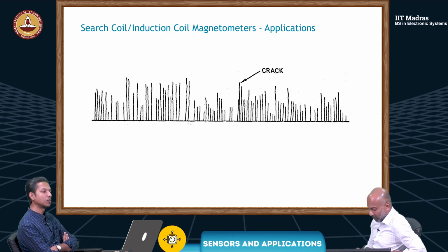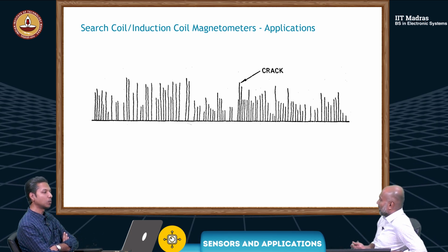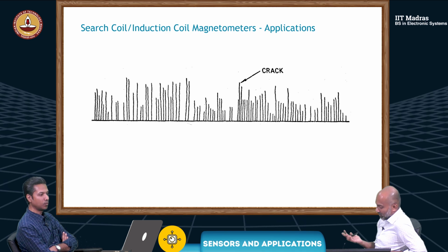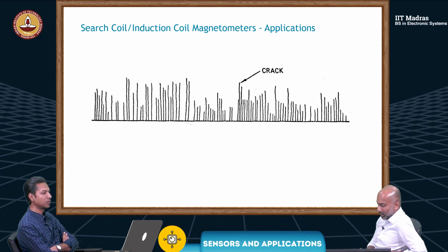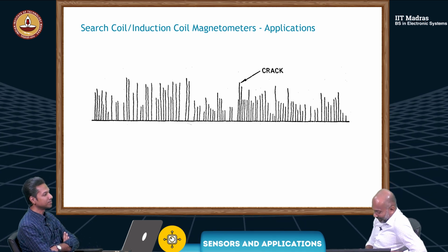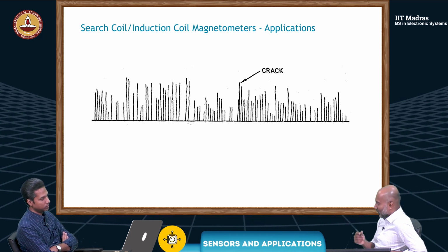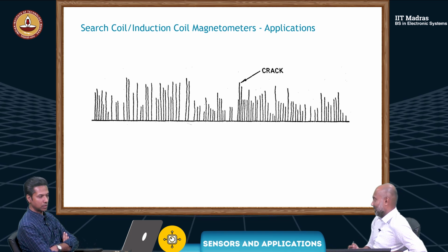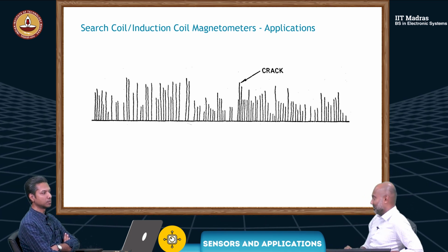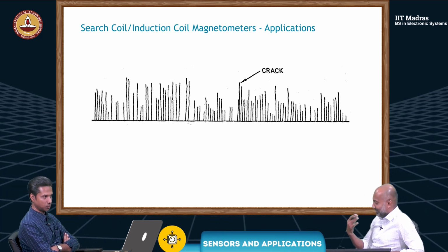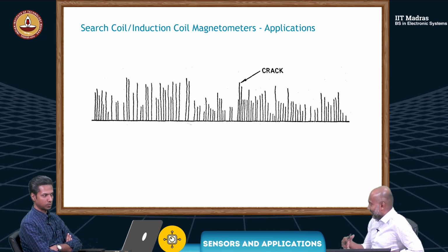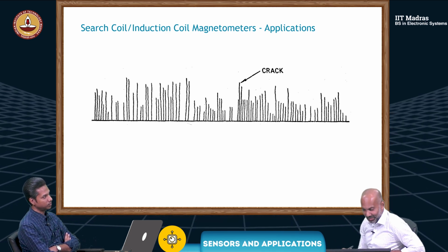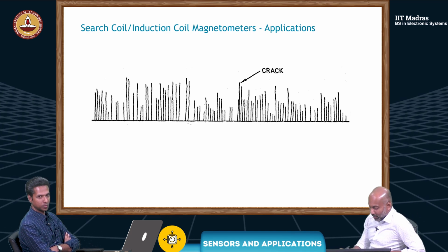Now, we have already talked about 3 different variables, right? Conductivity, permeability, and liftoff. Now we're talking about cracks. Now, we talk about the problems with the eddy current, is that we have too many factors affecting the test, right? Temperature, vibrations, applied stressors, internal, external, electrical interference.